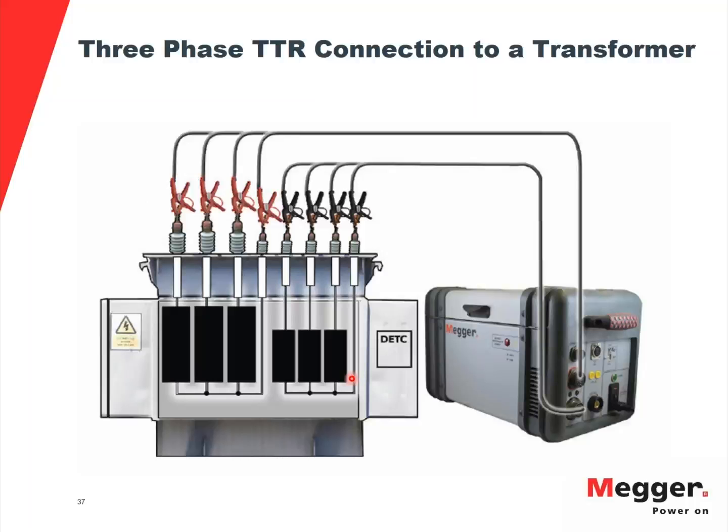But sometimes what you may have is that you may not have equal distribution of voltage between the taps. And then what would happen is that if you were to do the TTR test, you would fall outside of 0.5% tolerance. And as long as it is consistent on A, B, and C phase, you should be okay. Or as long as it matches the commissioning results or factory results, you should be okay. But keep an eye on those things.